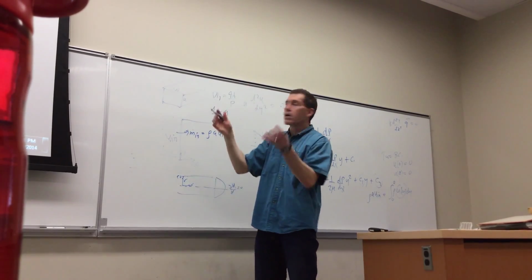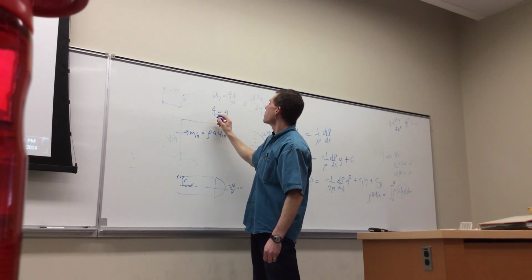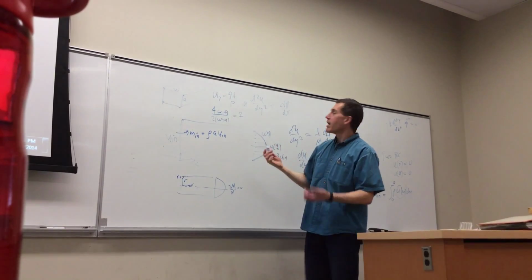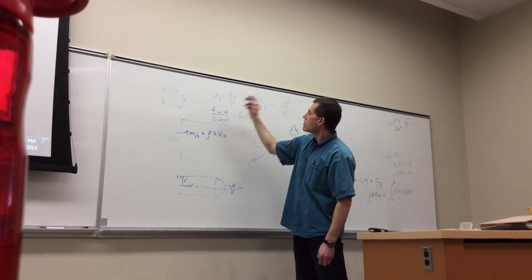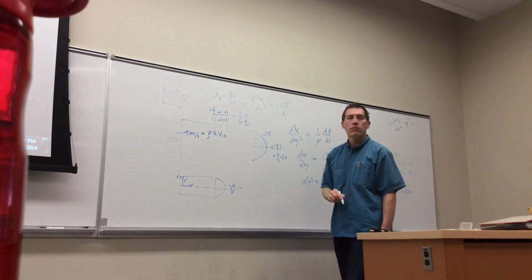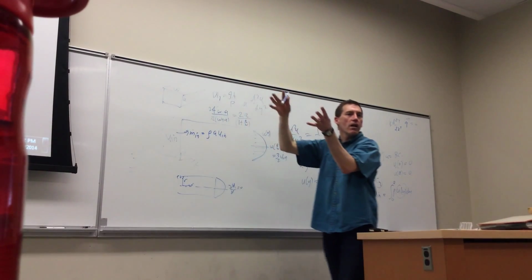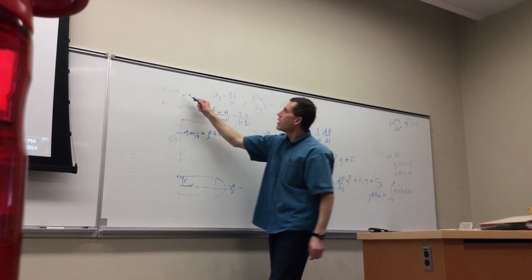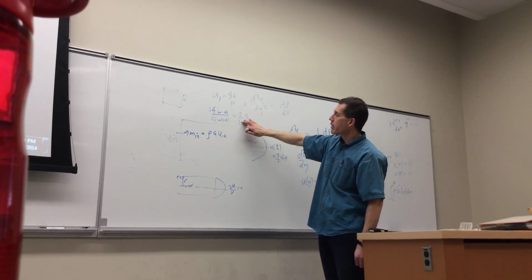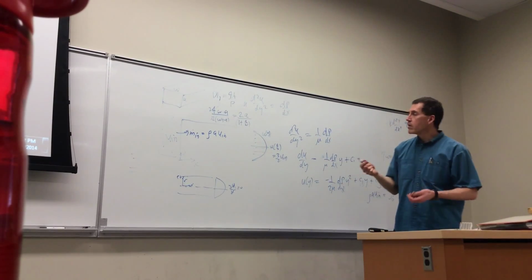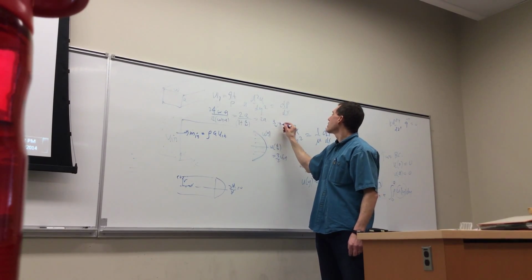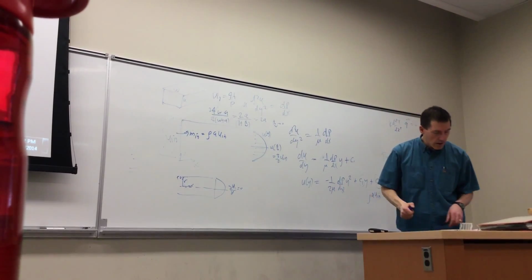So let's take a whole duct, a real duct: W times A, and then the perimeter is 2 times (W plus A). So the 2's cancel, and that's 2. Now, if I divide the whole thing by W, I get 1 plus A over W, right? So if I have parallel plates, W goes to infinity compared to A, so this becomes really, really large. This term drops away and it's twice the plate spacing. That's the hydraulic diameter of parallel plates, twice the plate spacing. That's what you would use in a Reynolds number for parallel plates. So this equals 2A for A over W goes to 0. So that's the hydraulic diameter.